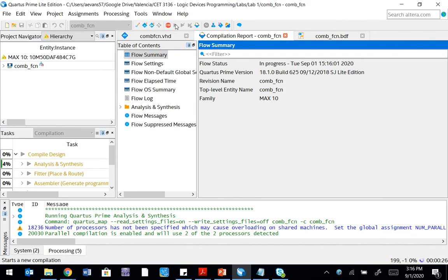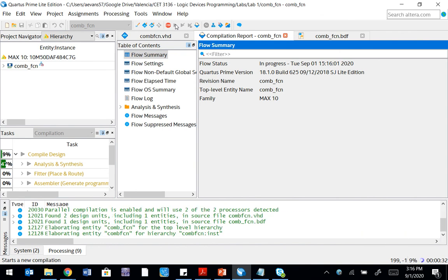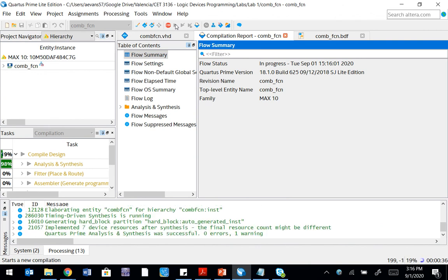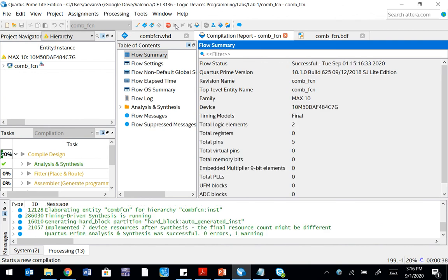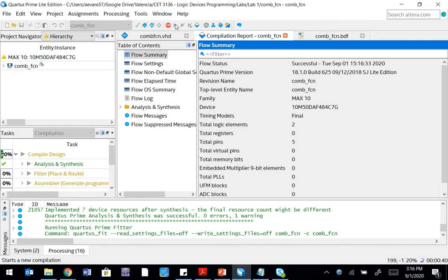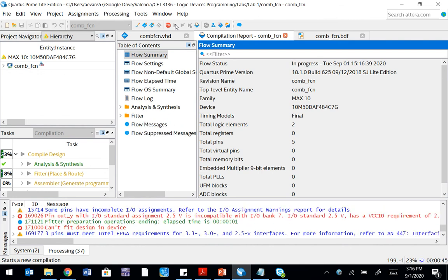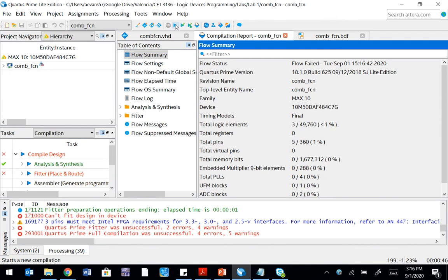You'll notice when you plug it in that a default program is always going to run where it just scrolls through numbers on the hex display. That's always going to be the startup program until you program the PLD. So right now we've got it plugged in and we are waiting for the compilation to finish. You're always going to have to do that second compilation after you add the pin numbers.